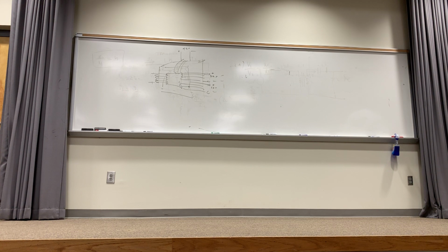The book gives a lot of problems where it's got weird currents coming in and stuff. Should we just change that all to the standard that we use? Like currents going out of one dot or into the other? Should we just change it back? I tell people, when you're doing mutual coupling circuits, current always into the dots, I1, I2, voltage always positive at the dots. When you're doing transformers, on the primary side, currents into the dot, on the secondary side, currents out of the dot. But V1, V2 are the same as for mutual, all right?